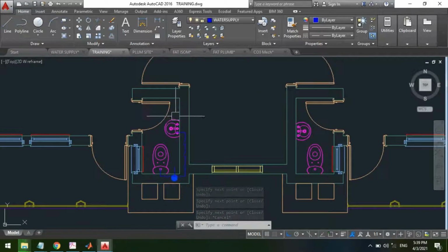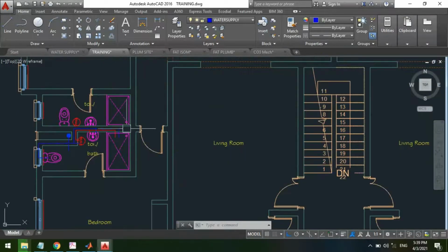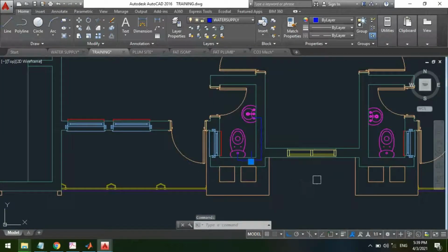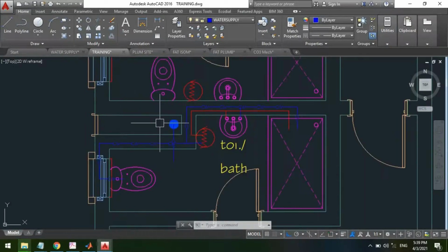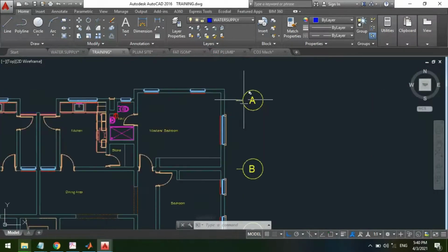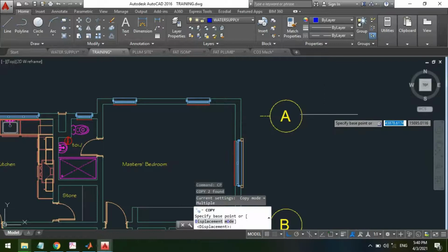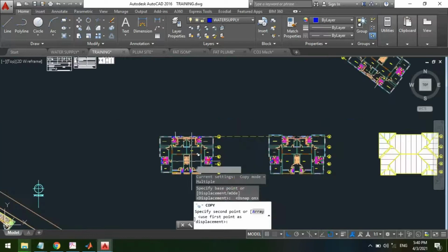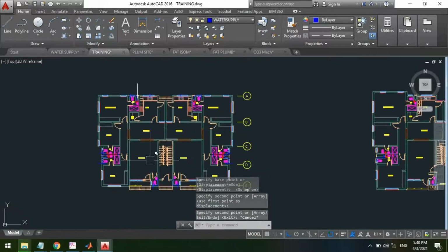In this instance, being a visitor's toilet, we are not required to design for the water heater. However, the next process is just to consider where the risers are coming from, since we are using a ground distribution network. The way I achieve this is that I will highlight all the risers, and since I've already aligned my hiding lines over here, I'll use this hiding line, CP to copy to the ground floor, F3, while I come over here and I paste.